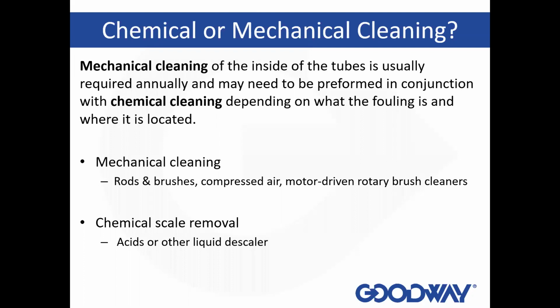And at the same time, it's hooked up to a high flow soot vacuum. And it's important to make sure that you have the right type of vacuum too. It's not the place for a Home Depot shop vac. One, because the filtration on those isn't really meant for soot, for going down to 10 microns and filtering that soot so that it's not blowing back into the air or hurting the carbon brushes in your motor and causing the vacuum to fail. And two, because you're talking about picking up light materials over really long distances.